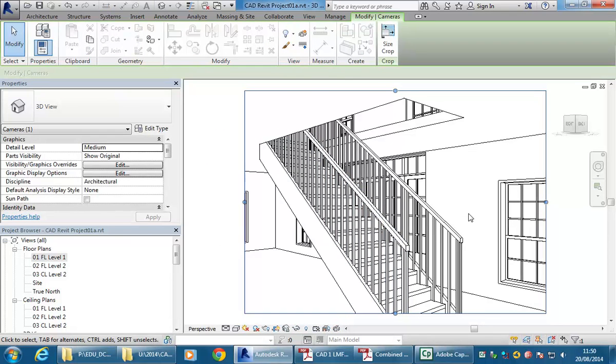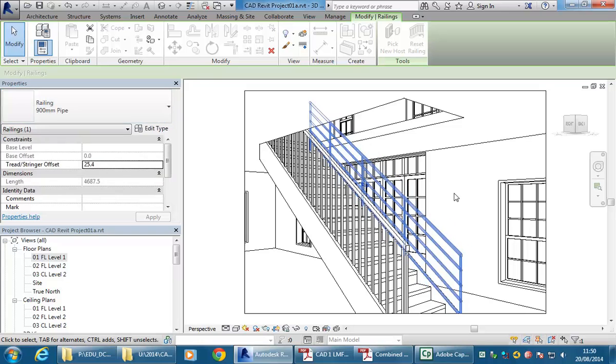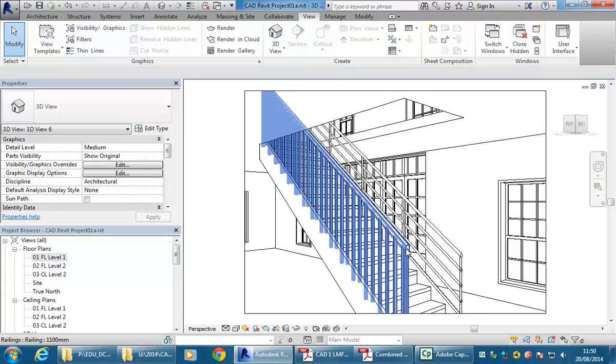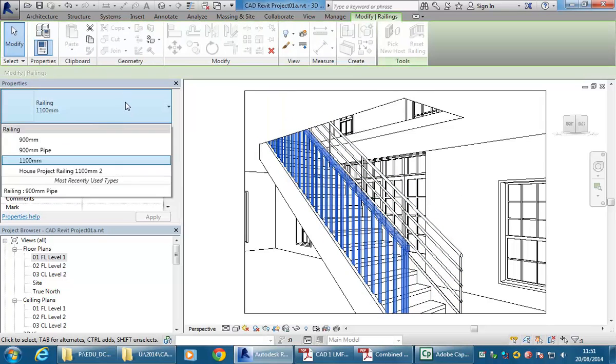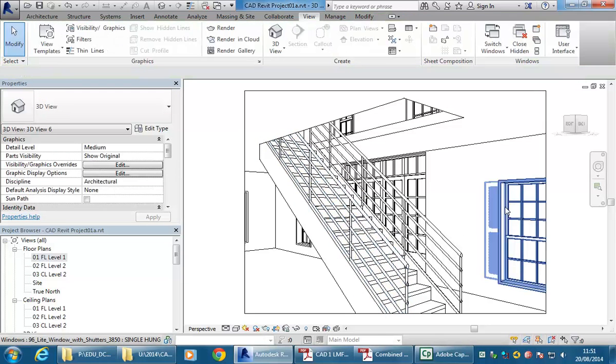And notice it gives you a railing automatically on the sides of your stair. And those railings can be set to the same ones as any of the others. So when you select them, you can just in properties try out the different preloaded ones. So that's a good thing to try.